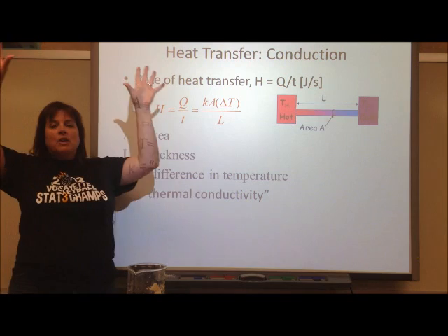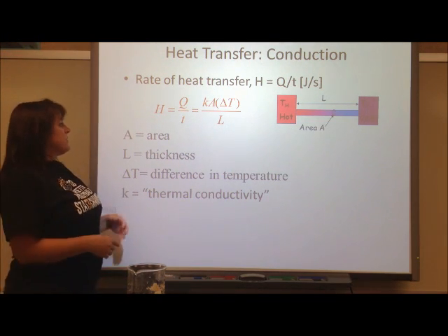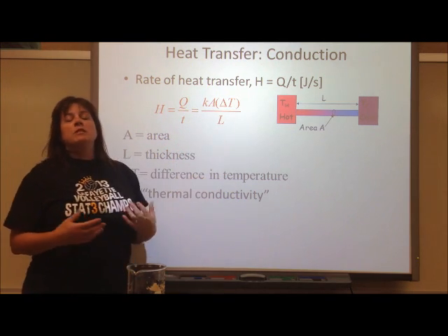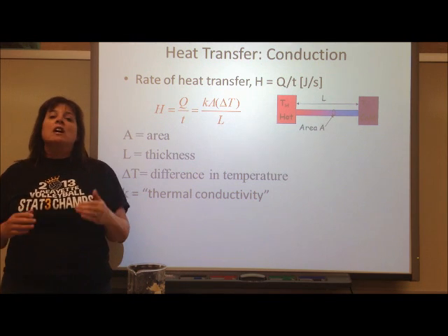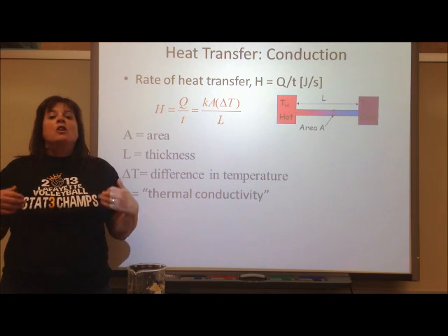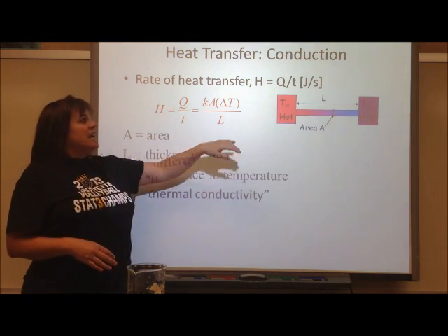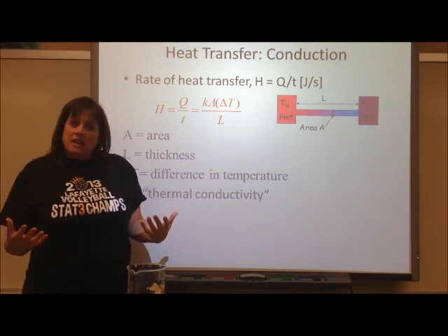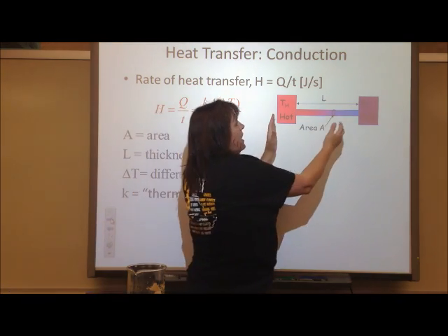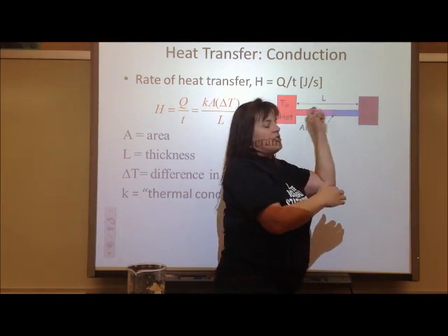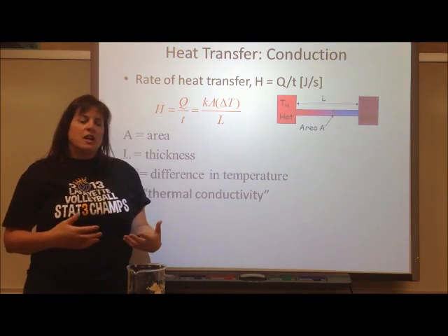Times the area. So the bigger the area in contact, the quicker that heat is going to transfer. Times the change in temperature, the difference in temperature between the two sides of the material. So the greater the difference in temperature, the faster the heat is going to transfer. And then divided by L, which is actually the thickness of the material. How thick is the material? How far do those molecular collisions have to go in order to have that material transfer heat in a certain